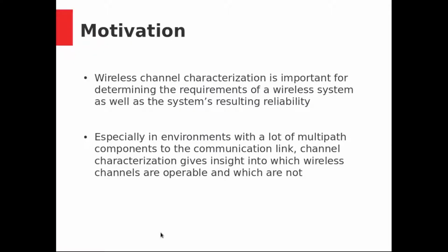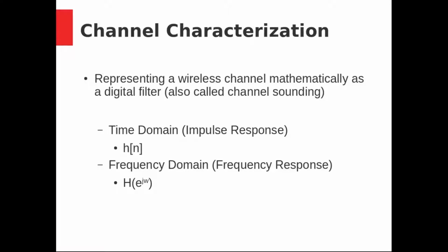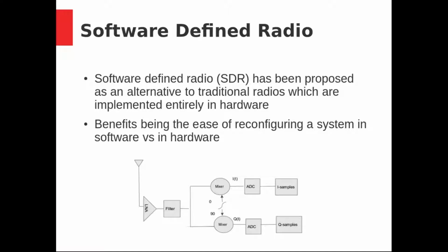Wireless channel characterization is important both for determining the requirements of a wireless system as well as the system's resulting reliability, and it's especially useful in environments with a lot of multipath. The goal of channel characterization is to represent your wireless channel as a digital filter both in the time domain and the frequency domain. Software-defined radio has recently been proposed as an alternative to traditional radios, where you implement things entirely in software instead of hardware.